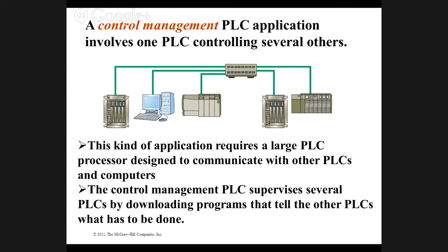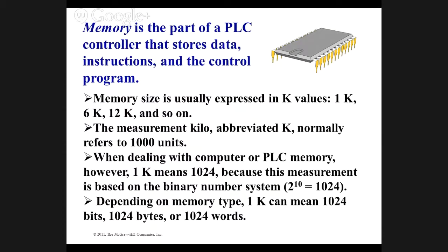Memory. Memory size is usually expressed in K values, 1K, 6K, and so forth. We will use the measurement kilo, abbreviated K normally. It refers to 1,000 units. So when dealing with computer PLC memory, however, 1K actually means 1,024 because this measurement is based on the binary number system. So basically, that's the number you end up with. The maximum number in binary is 1024.